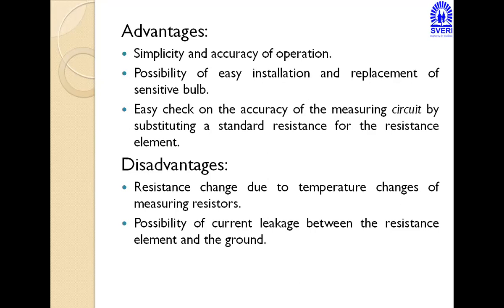That's why there is leakage of current from the resistance element to the ground, and that's why the output or answer is somewhat incorrect. This is the main disadvantage related to RTD.